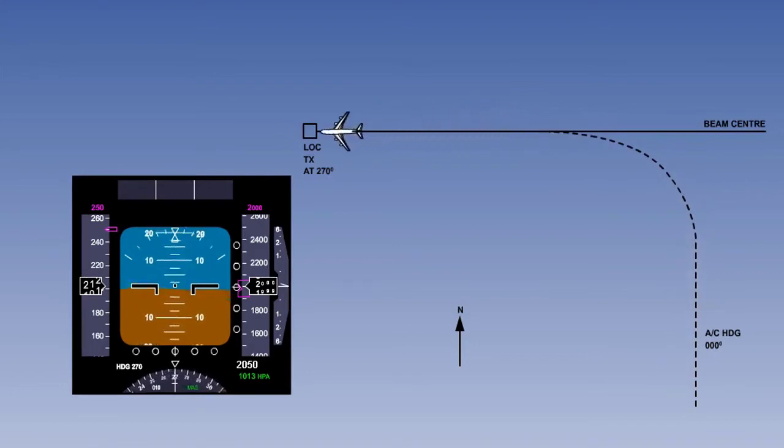the opposite side. A flight director computer takes this same raw information but processes it, working out the rate of change of deviation. This additional data allows the system to anticipate approaching the required horizontal or vertical flight path, and therefore it can adjust the amount of roll or pitch input so that the aeroplane smoothly intercepts the flight path and does not fly through it.